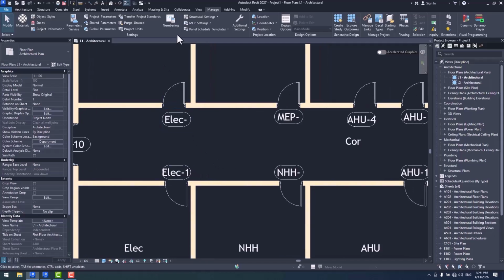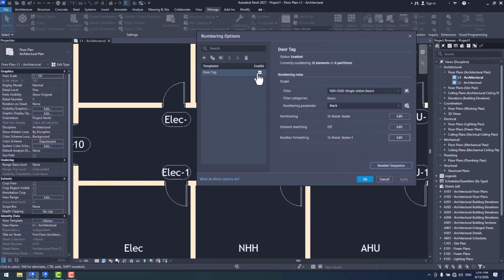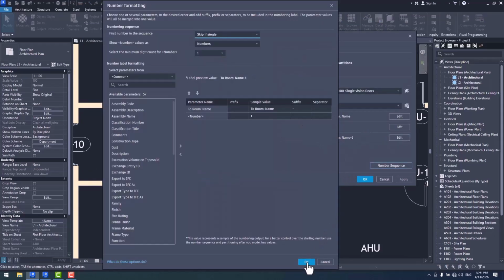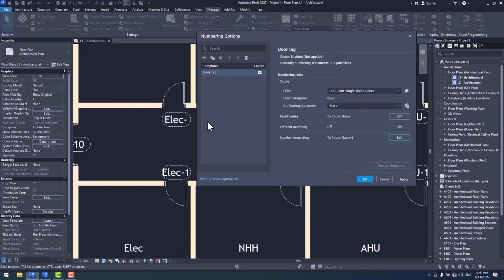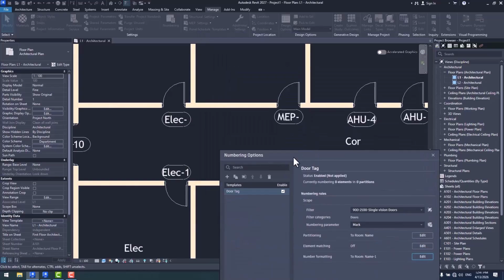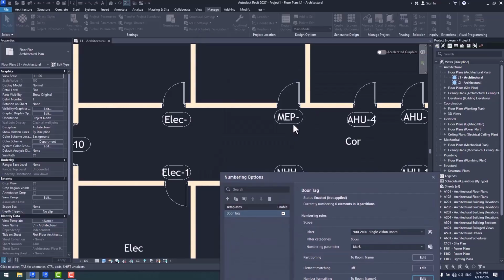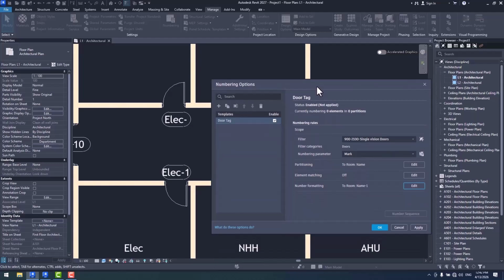And then we also mentioned a third option, guys. Skip if single. You know what, guys? Let me try putting this in another way. The difference between these 2 options, I'm talking about skip and skip if single, is the fact that using skip, when we are trying to specify codes for multiple elements, the first element won't get any numbers, and then the previously second element would become element number 1, in fact. Well, basically, single elements will be skipped.